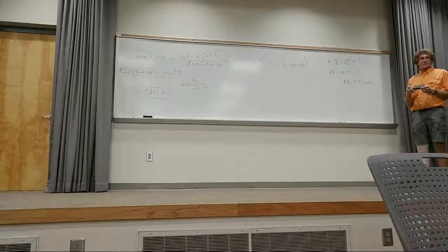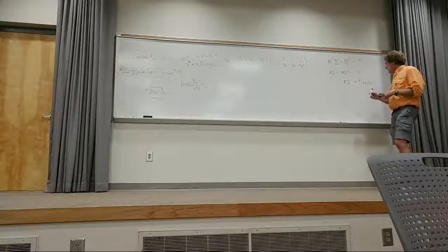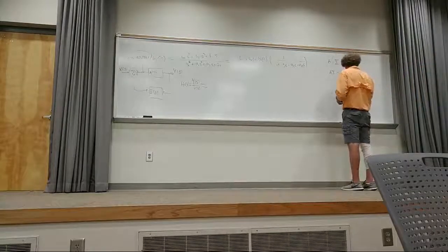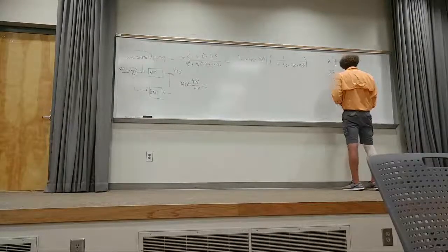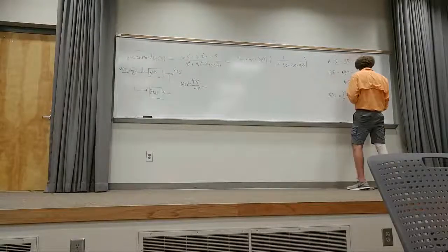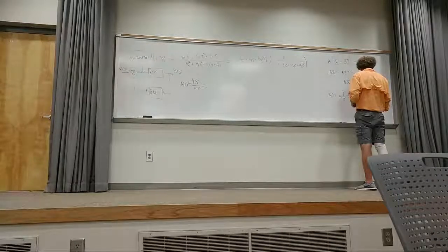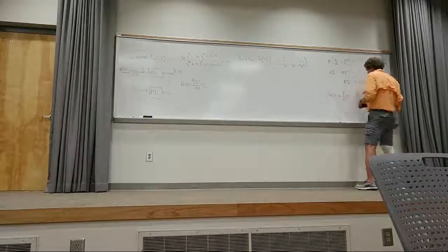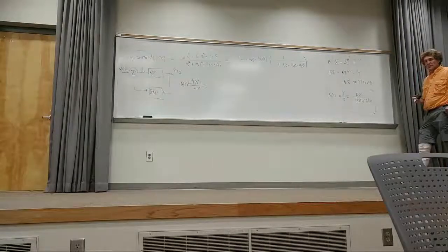Just rearranging terms. Y'all agree with that? So what's the ratio of Y over X? Y over X, or output over input, or the transfer function, which technically is H of s, is equal to A of s over 1 plus A of s times B of s. And that's the transfer function for that network.